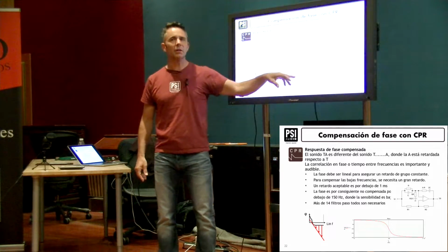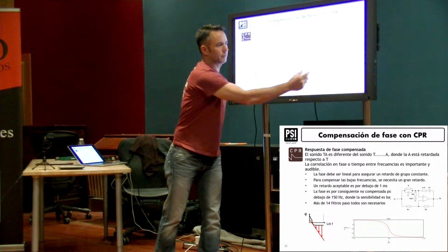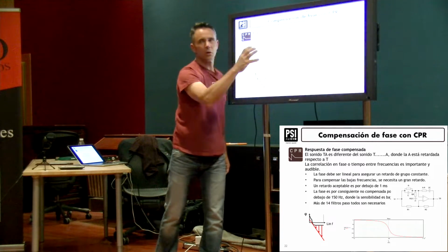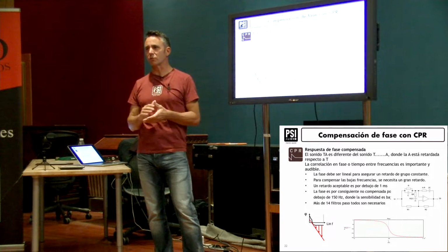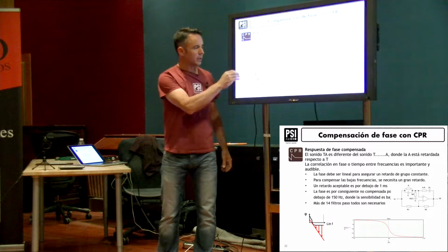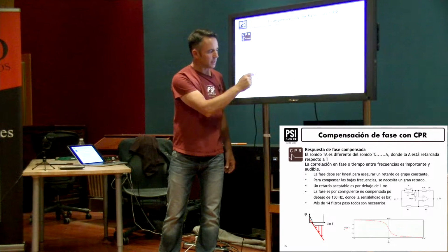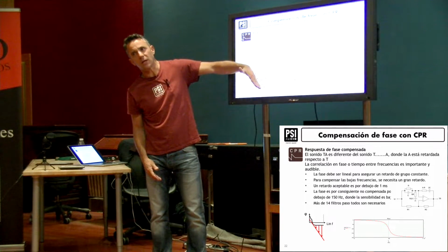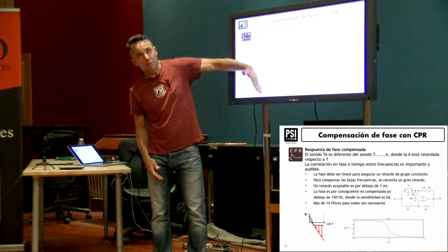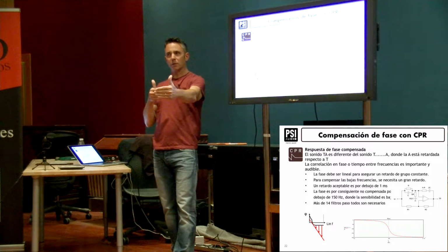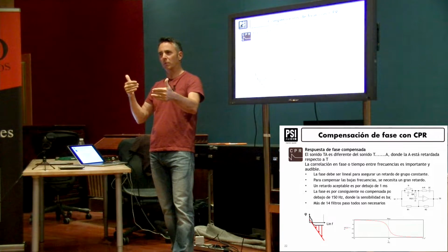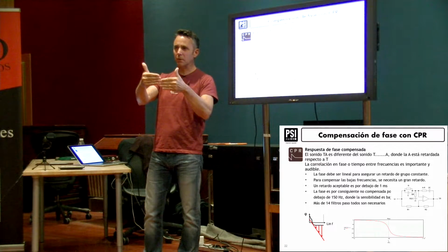And yeah, an all-pass filter is a filter that's going to affect the phase at certain frequencies without affecting the frequency response. So this will have this kind of response, and you need lots of these filters to come back to a linear phase response. So linear phase response, this is what you call it. So the phase is like this, and you want it linear, and basically it can be like this or like that. That's just a time delay factor, and that's the same. So if it's linear phase, of course if you go back half a meter, there'll be a phase rotation that's longer on the high frequency, but that's linear, so that's not a problem. But you want it coming out the same, at the same time.